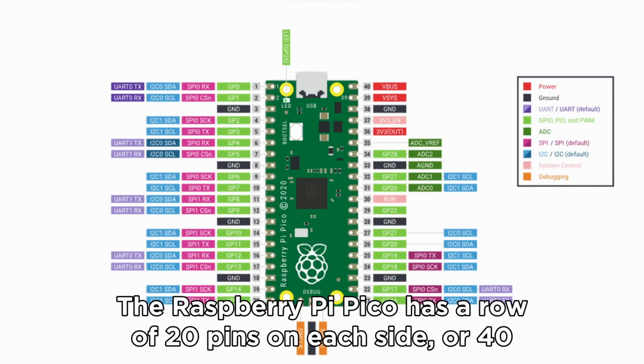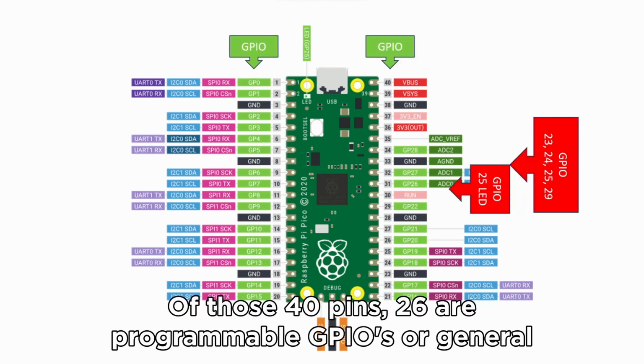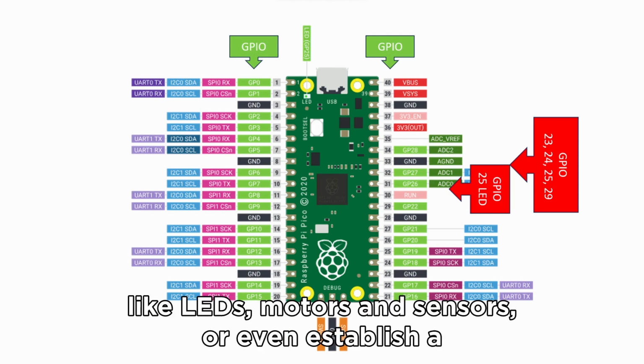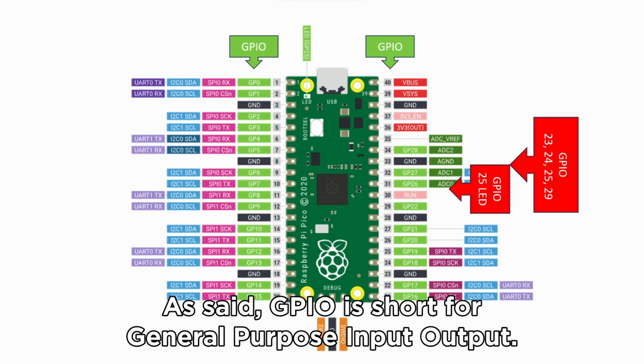The Raspberry Pi Pico has a row of 20 pins on each side, or 40 pins in total. Of those 40 pins, 26 are programmable GPIOs, or general purpose input-outputs, that you can use to connect peripherals like LEDs, motors and sensors, or even establish a communication with other microcontroller boards. As said, GPIO is short for General Purpose Input-Output.